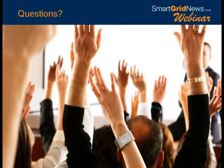Interesting. Okay. So maybe for Matt or for Chandra, from Louisa, she noted that you're pulling the data from the head end and from the customer information system. Why not from the meter data management system? Was that a technical architecture decision? It's kind of a philosophy: do you want to take VEE data, which is industry vernacular for validation, edits, and estimates. You want scrubbed data, in other words, but you want raw data to then trend on.